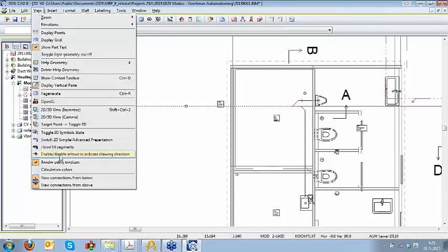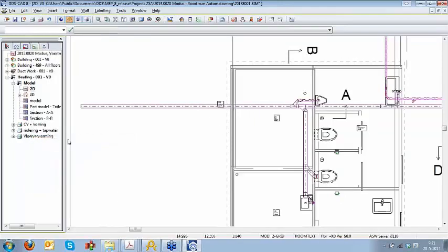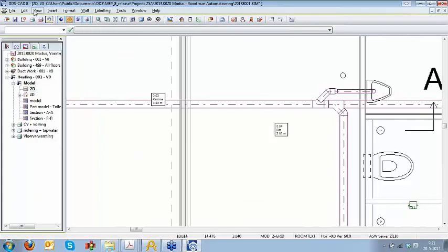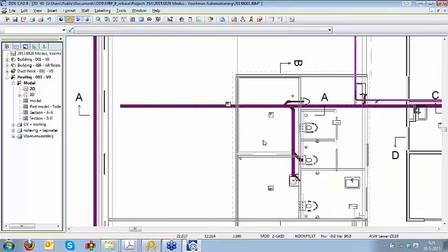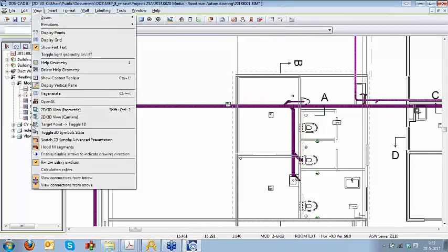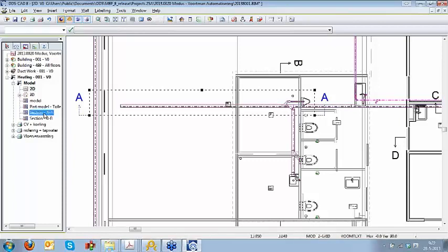Because of the object structure, we know that a pipe of 110 millimeter will be used for our sewer system. We can also show in 3D, and another view which we can have is a colored view, which will be represented on our top view of the building. So I'm using a section view on section AA, and this will give me a side overview on the slope which is set in this area.